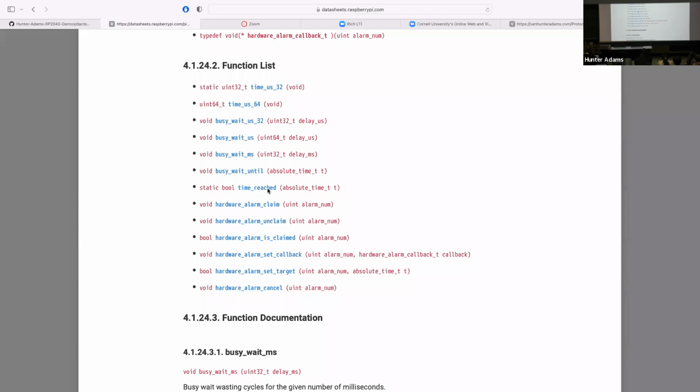Now, what might you do with a capability like this? The fundamental capability here is you write a value to one of those alarm registers, and when there's a match, that interrupt fires. And it won't necessarily fire again unless you rewrite the value in the alarm register. Otherwise, it just goes off once, right?